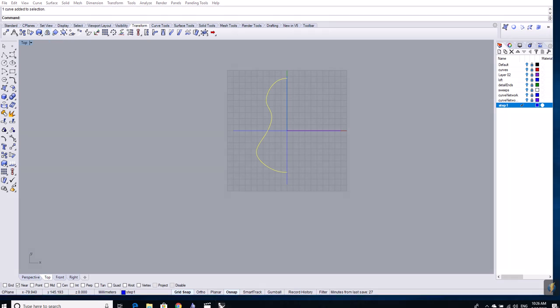With the mirror tool, remember, everybody's learned how to use that. If I click on it, here's where I'm using my construction lines, because it's asking what is the start of the mirror plane, and then what is the end of the mirror plane. It's snapping to that construction line, and then I get what I want, which is a symmetrical closed shape where the endpoints of each of these two lines touch, so that there's not going to be any holes. Because for the next tools we're going to work with, if those lines don't touch perfectly, it can be a real problem. The tools won't work well.